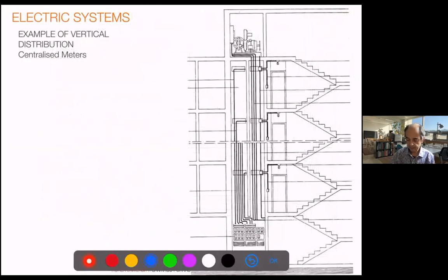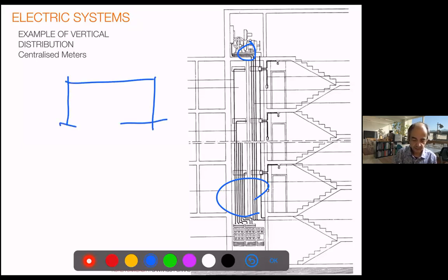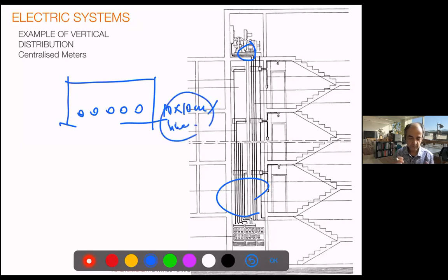And this is the example of the shaft with all the individual cables for each of the elements. See how the elevator is 3-phasic, so it has the 3 cables going there, plus neutral. In this case, for the shaft, the system is the same. You may count about 10 by 10 centimeters per line, and you are more or less in dimension, right?